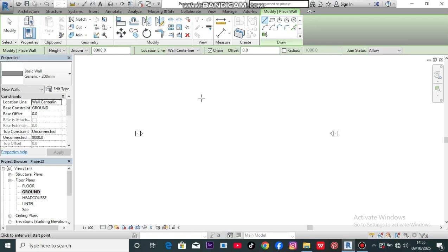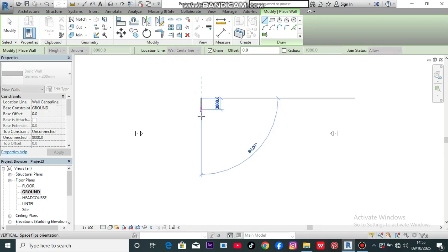Let's come here to this point and left click, drag it all down. When I'm moving my cursor, you could see that it's writing some little numbers beside it. So this shows you the dimension of your line, the wall I'm drawing. This is the dimension 5,000. It means 5 meters. When I move down, 9 meters, 100, and all those.